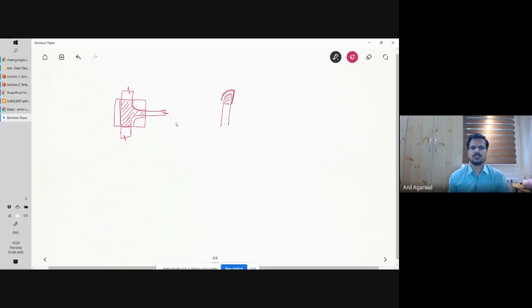So what you see here is that either the thickness is high, or because there is a corner, you get a larger surface area. Where your surface area to cross-section area ratio, or surface area to mass ratio, becomes high, those portions start to cool down quickly. In the middle of the web, for example, you have this much cross-section area and this surface area.